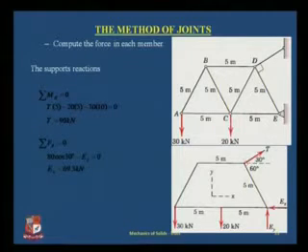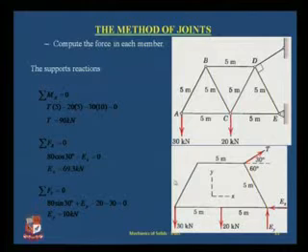And I have force T which is going this way, sorry, these two forces are anti-clockwise, this is clockwise, so I have taken clockwise as positive, these two as negative, from which I will get T equal to 90 kilonewton. Once I have got T, I solve it for summation Fx equal to 0, from which I will get the force Ex. And from summation Fy equal to 0, for the complete truss, I get Ey equal to 10 Newton, which is a simple thing which you have already done in your simple beam chapter.